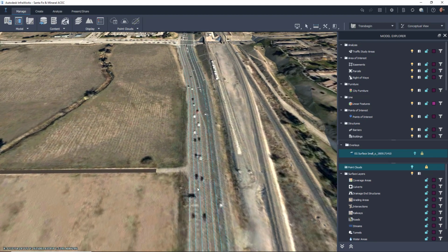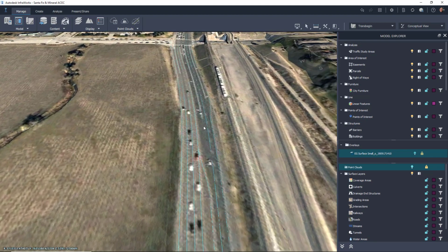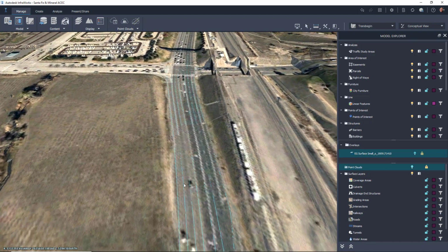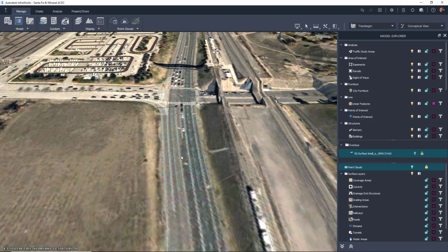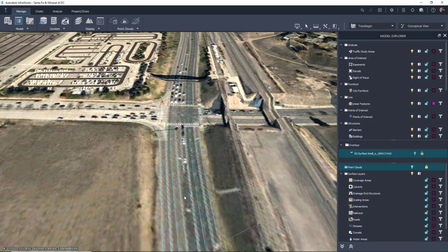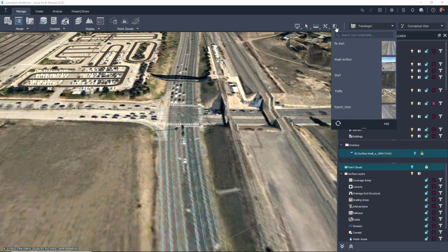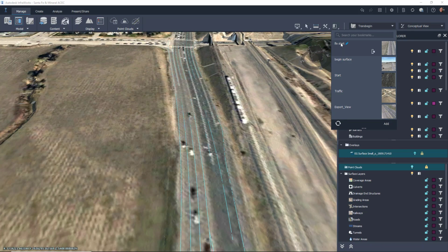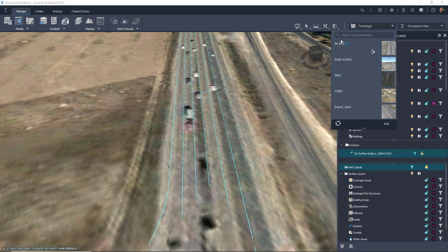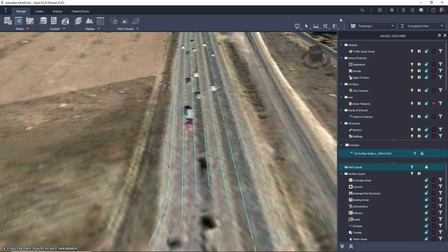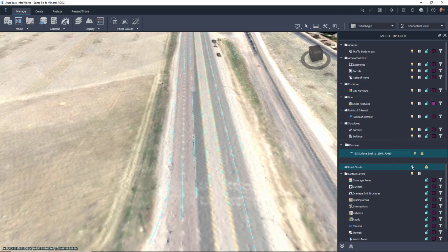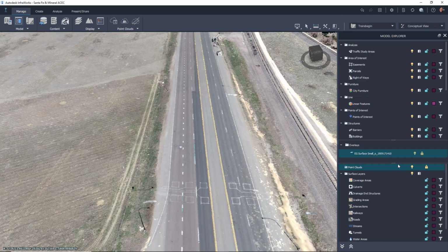You can see that they run all the way to the existing intersection, but then stop at the end of the markings themselves. Now I need to generate what is called transverse features from my surface. These transverse features will help me to create a lightweight surface from the point cloud without losing any accuracy that I can use inside of Civil 3D. This will make my model in Civil 3D, where I do my design, run more efficiently.